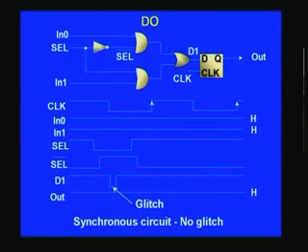And another thing we talked of earlier is the glitch, which is an unwanted, uninvited guest that you would like to eliminate. So for example, this circuit gives a glitch as far as this combinational circuit is concerned, and a narrow pulse like this is known as a glitch. How it is produced, we'll just have a look. These are all plain AND gates here with an inverter here, and then finally these two are ORed here, and then applied to a D flip-flop.